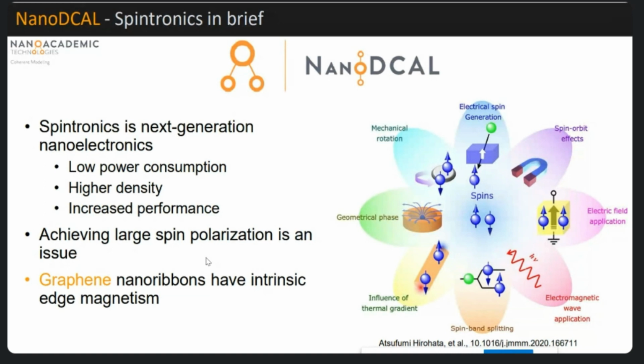You want to fall the light on the middle region of your junction. You can also perform photon absorption and calculate the photocurrents. So spin polarization, spin up, spin down calculations, and some spin transport calculations can also be performed. You can simulate a single layer of graphene, armchair, zigzag, magnetic effects, magnetic properties, atomic texture, and magnetic moment per atom calculations. All these things, as you can see here, can also be helpful to create such devices,